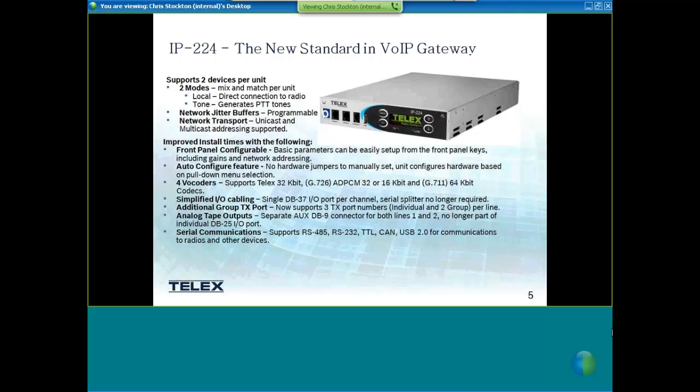We do have an auto configure feature. This is a pretty slick feature. So if we are connecting to a known radio system that we are known to work with, like typically Kenwoods that we mostly work with, we can automatically configure the jumpers, like the hardware settings for you, the levels, and so really, you just change the serial port params, and it'll automatically configure, in this case, we'll say a 7150. You could change the serial port params to that, and it'll automatically set your hardware and levels to what we recommend here to be set up in the factory.